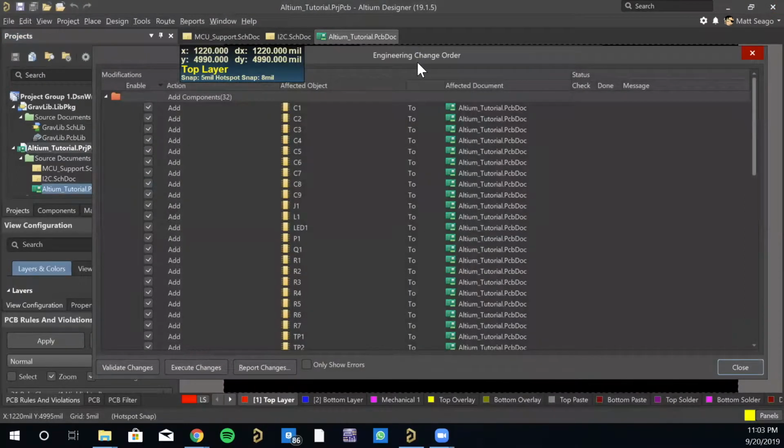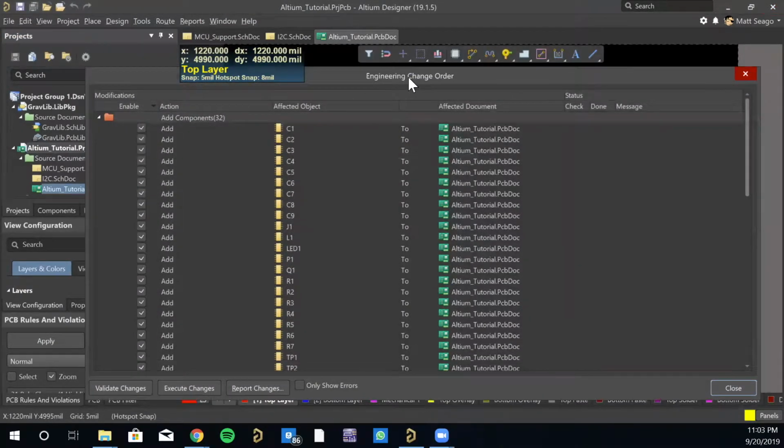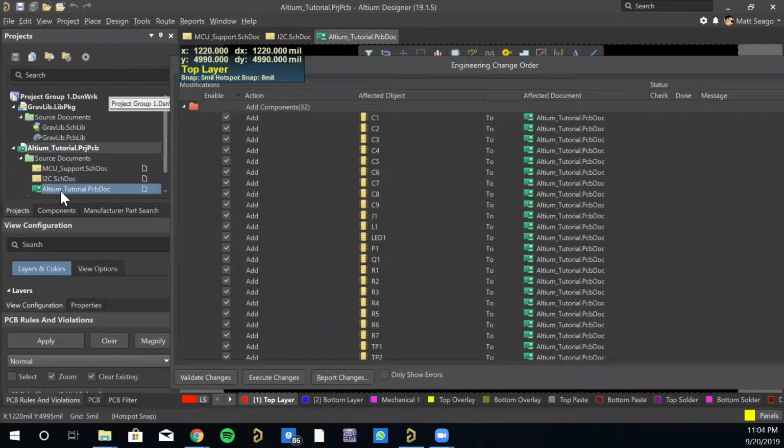Okay. Great. So what I was getting at was the problem it popped up will sometimes occur if you don't compile the project. So be sure you do that. And I think, I could be wrong, but I think it's helpful to have the PCB document named the same as the project. You should only have one PCB document per project. You can have a ton of schematics though, at least for our purposes.